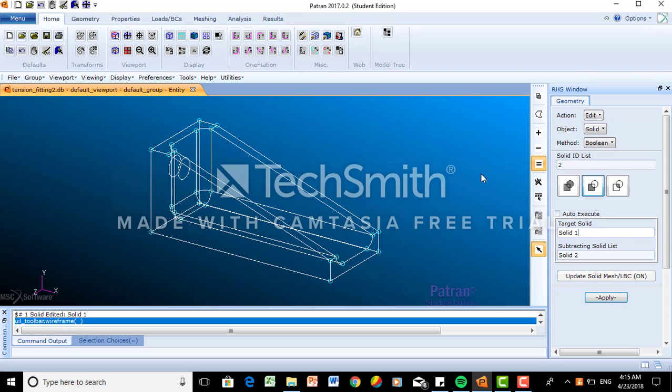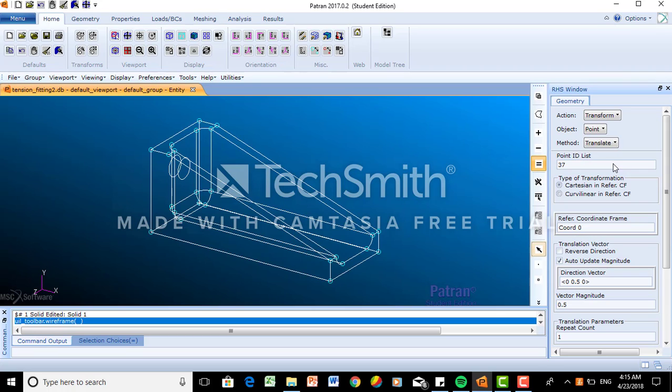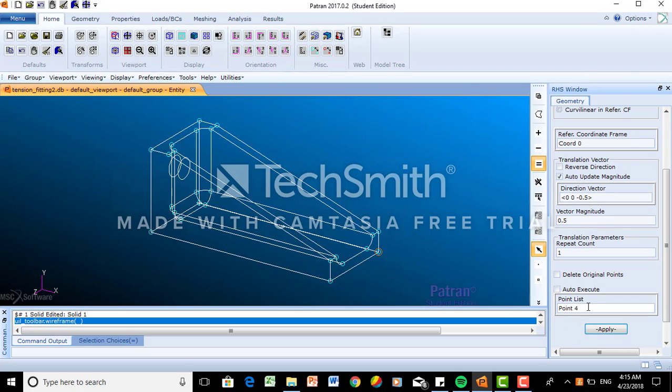Now we're going to click on the wireframe icon and make sure that Transform, Point and Translate are selected in Geometry. We're going to enter 0, 0 and -0.5 for Translation Vector and select the point at the base edge of the fillet. Remember to turn Auto Execute off. Then we're going to click Apply.